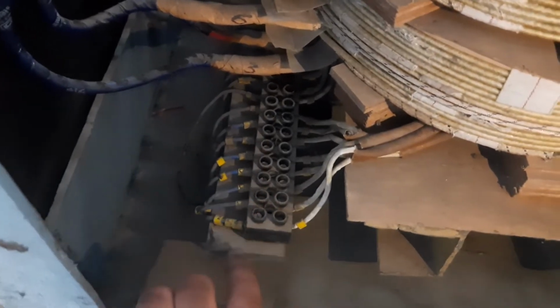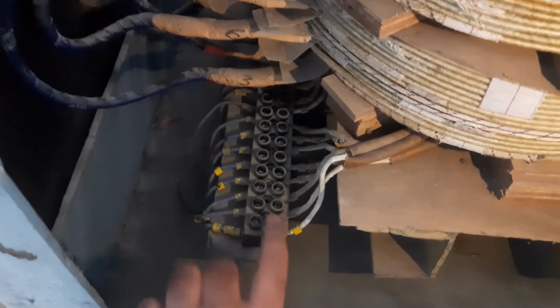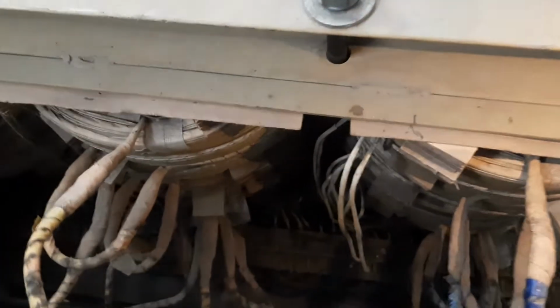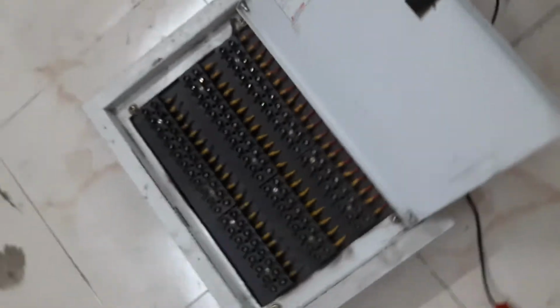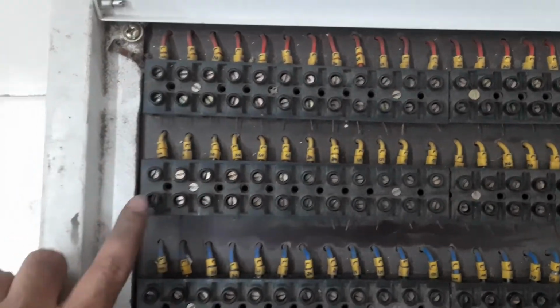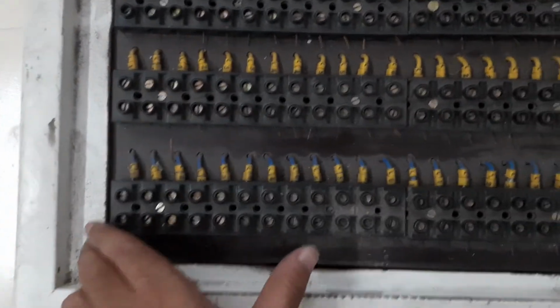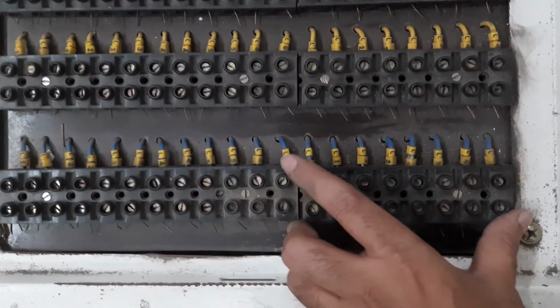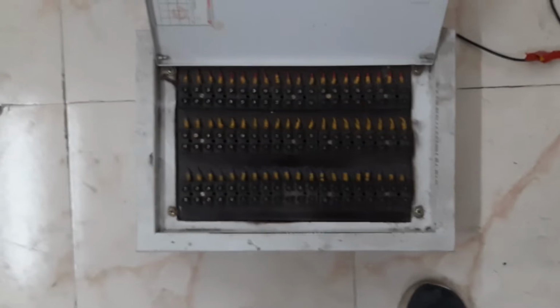Now for simplicity, these windings are brought out. We can see from this side, these are all the surge coil windings. These are brought out for the measurement of voltage. Here now you can see this red color is for the A, that is U phase, this for the V phase and this for the W phase. There are 6 coils wound on the HV winding, and 4 on the LV winding.